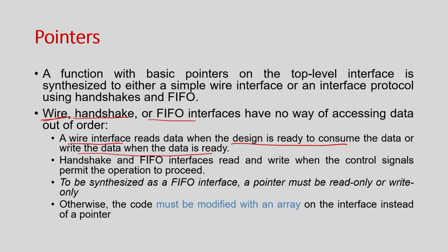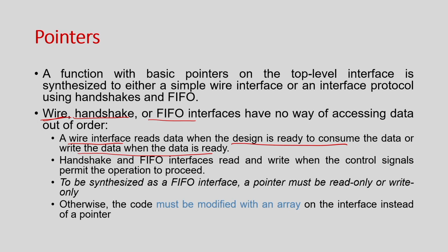The point I am trying to make is that once you have declared a pointer, the high level synthesis tool tries to implement it either as a wire, where it just makes the handshake with data valid signals, or as a FIFO. If it is a random access, it won't be able to implement that. For both handshake and FIFO, read and write should be in the same order. If it does not follow that, the tool won't be able to implement the FIFO, handshake or wire.